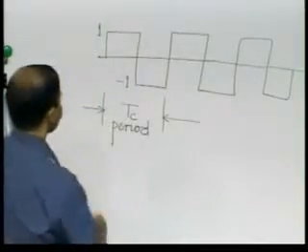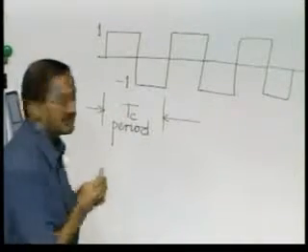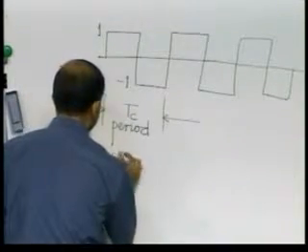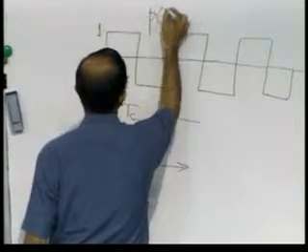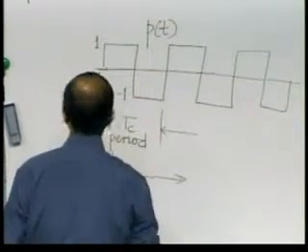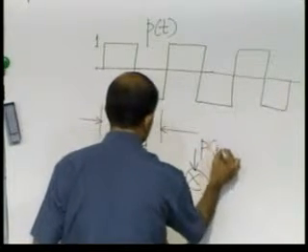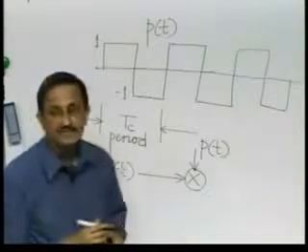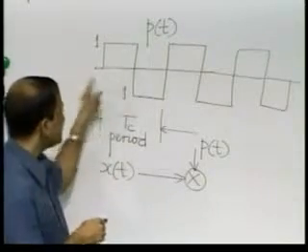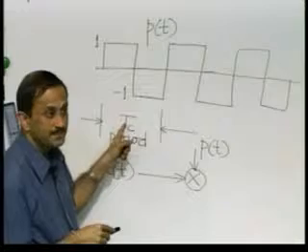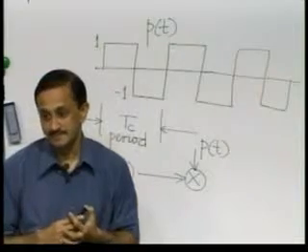Right. Anyway, so suppose we happen to multiply our incoming waveform, let us say the waveform is x(t), with this gating pattern, let us call it p(t), right. So, we multiply x(t) by p(t). Now, let us assume that x(t) is band limited. And let us assume that the frequency of p(t), namely 1 by Tc, is much larger than twice the maximum frequency component in the waveform x(t), right.